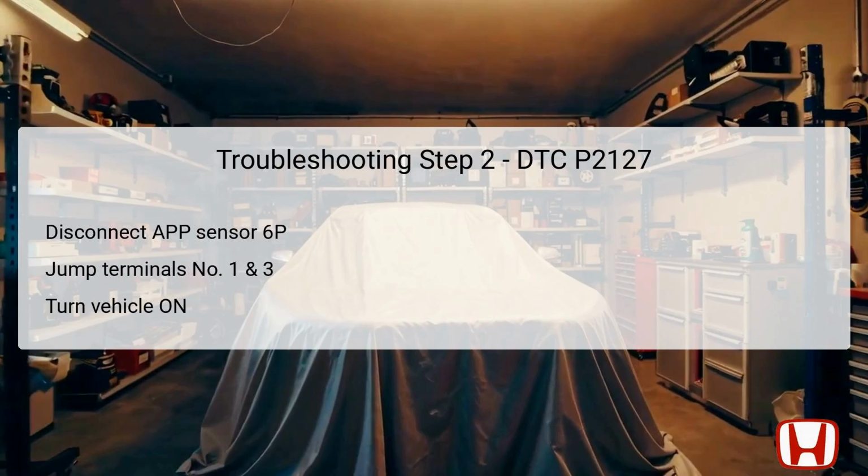In this step, the technician will disconnect the APP sensor 6P connector to prepare for further testing. By jumping terminals number 1 and number 3 of the connector, this bypasses certain connections, allowing for a more direct assessment of the sensor's function.